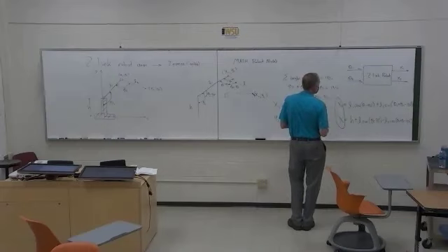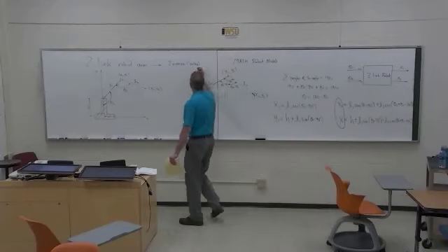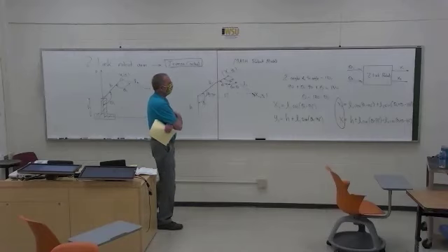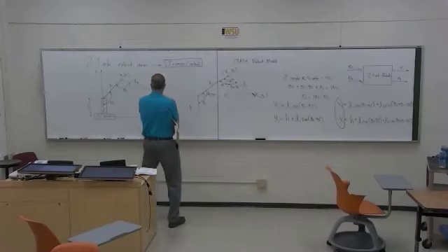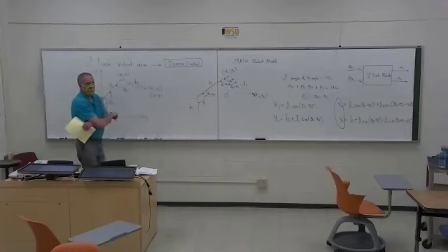So that's the system. What does it mean to do inverse control? It means that we want to invert that. We want to say, I want to put the end effector at a location, say 10, 5. If I put that into the controller, the controller is going to figure out the thetas that are needed to put the end effector in the spot that I want.